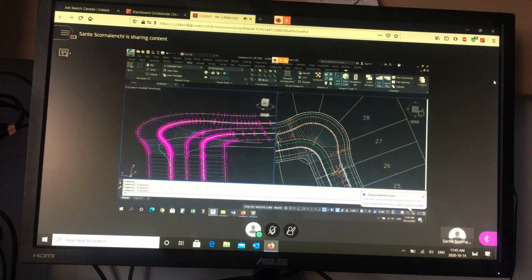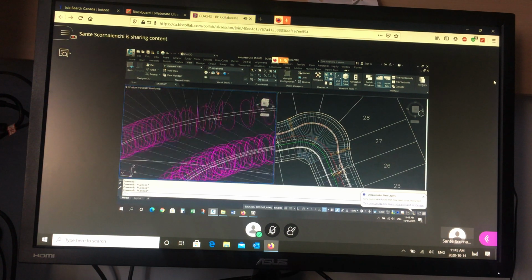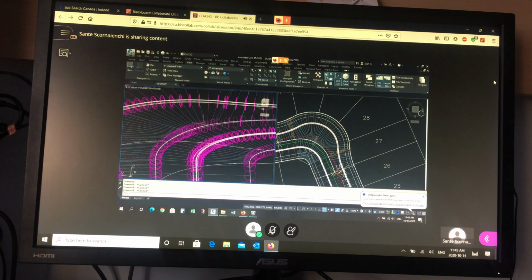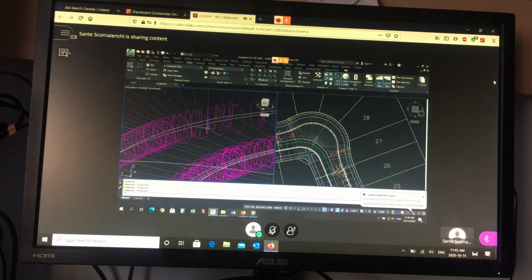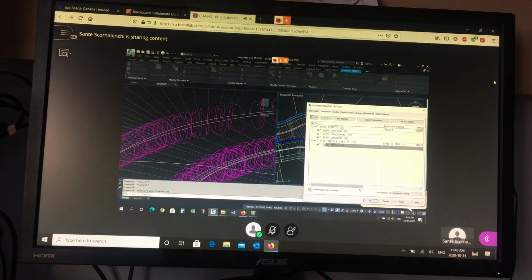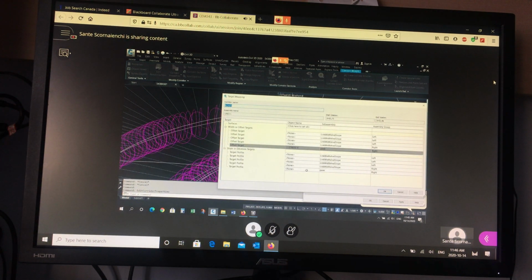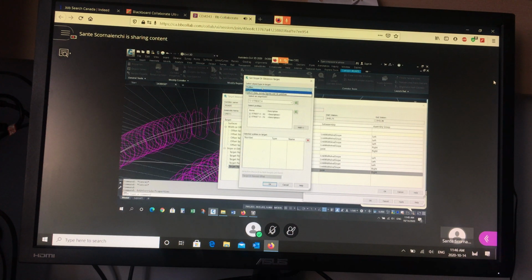So now you have to give it a vertical target. So I want to close that gap. These widened pieces just got longer, maintaining the 2% that I originally put in the cross section. So what I want to do is make these ones not only stretch to center horizontally, but now match the center line elevation vertically. So then we go back to the targeting for this piece here. And I go to target for this piece. So I have the horizontal target. Now I go to the elevation. I go to the last one, and I say, okay, go to that road. Right? So go to the profile for Street X, the main road, right? And find the finished ground, the design profile of the road. Add that to your instruction.